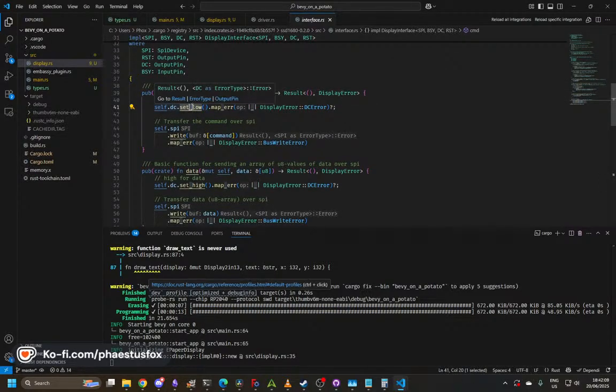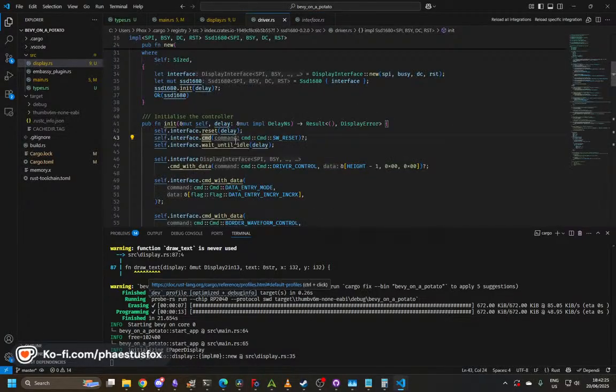If I remember, it's literally infallible because we're using a Raspberry Pi, and then transfer the command over SPI, which is when you write, and then I'm assuming you have a timeout. Do you have a timeout? Or you just say bus write error? Okay, but what are the errors? I'm assuming it's timeout. So I don't think we're getting... I think we're getting past here, and we're saying you're idle. The only thing is we connect to the oscilloscope and try and probe what the hell's happening.